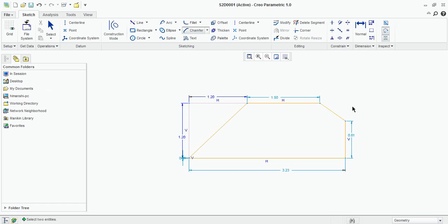It will give you variable sections, but if you want these edges to be trimmed, select chamfer trim. Select it, select the first edge and second, and you have the chamfer with trimmed edges. So this is all we have in this module. Let's stay tuned for the next section. We'll study the rest of the commands, practice this at home, and you'll be perfect soon.